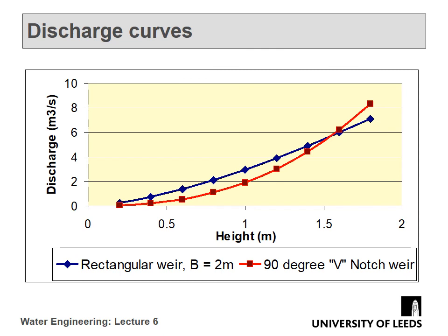For each weir you could draw a discharge curve, a height-discharge curve. Now this is quite common. There's a couple of different ones on here, and you can look at those and see how they vary very slightly. But the point is that as height increases, so does discharge. As depth increases, so does discharge.